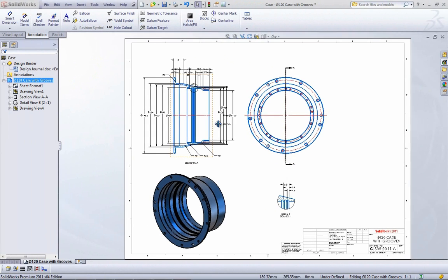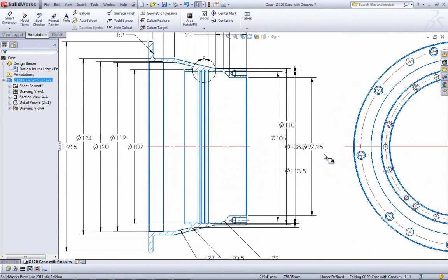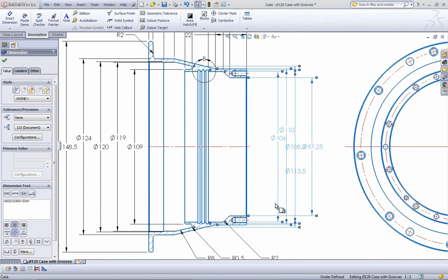If we look at this drawing view up on the upper left here, we have some dimensions all kind of running into each other at the moment. One of the new enhancements in 2011 for drawings is if you want to grab a group of dimensions, you can actually change the spacing on them. And you have this new line on the dimension palette to change the spacing itself. So you can auto arrange the dimensions, have them evenly spaced, linear or radially. You can have them collinear, you can have them staggered, top, bottom, left, right, justified.